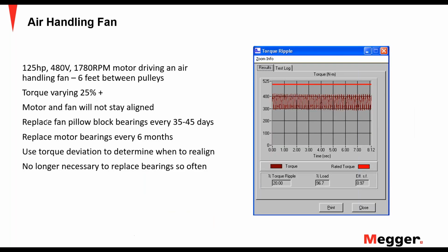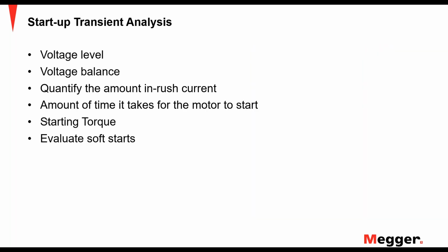So load related issues. Last thing here, I think we want to look at is startup transient analysis. We're going to look at your voltage level. Is my voltage balanced as I start this motor up? Quantify the amount of inrush current, the amount of time it takes for that motor to start. How long does it stay in that high inrush current time period? Starting torque. And it can be used to evaluate soft starts.